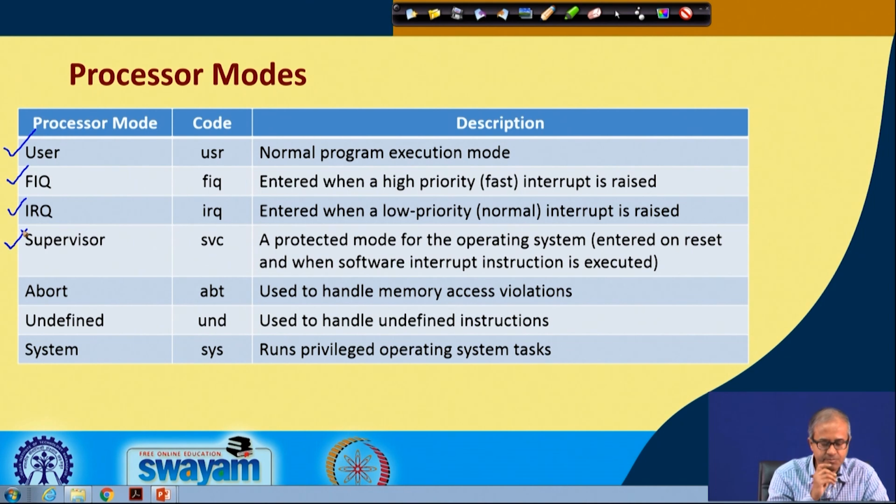Well, there is a supervisory mode which most of the modern processors have. There are some instructions like supervisory call, trap, or there is an instruction called SWI, software interrupt. There are various names to these interrupts, but the purpose of these instructions is that they are a way to transfer control to the operating system.